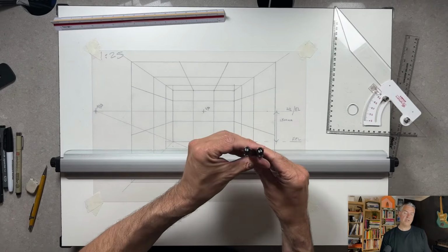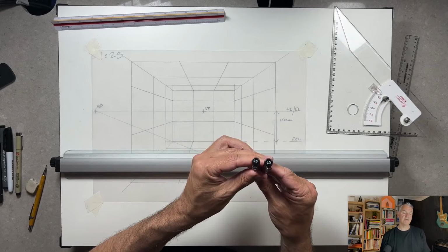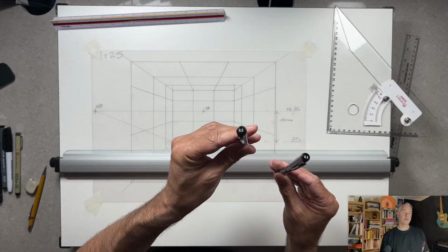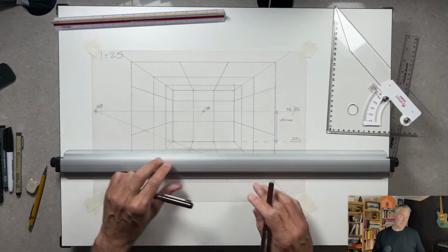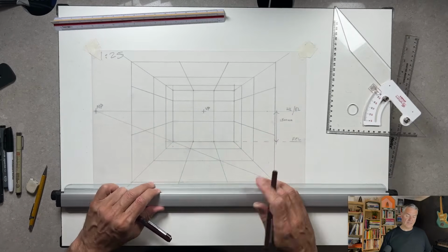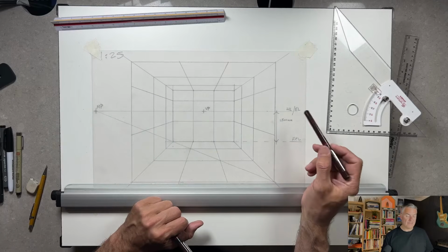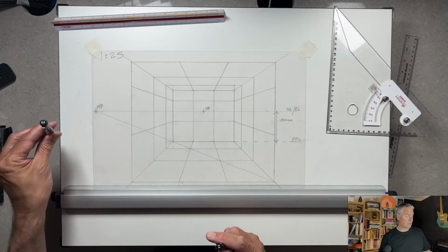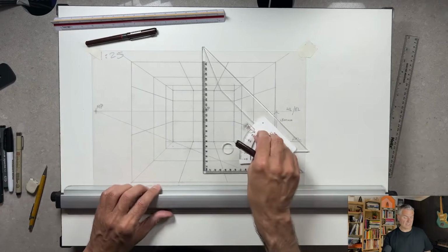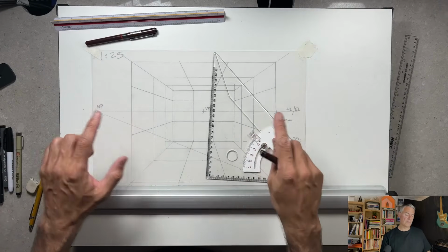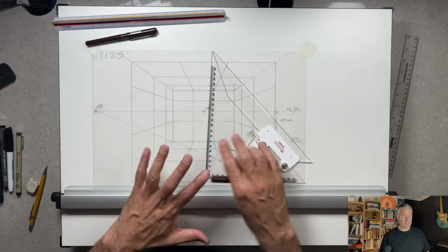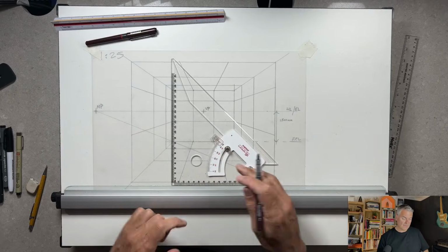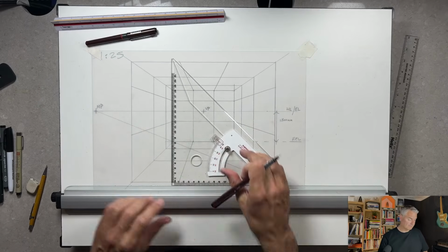So I'm basically going to use two thicknesses of pen here. So a 0.3, which is a little bit thinner than a 0.5. And so I'm going to basically draw the whole thing in a 0.3, and then I'm just going to fatten up some of the outer edges, which you'll see. So everything you'll see being drawn, I'm not going to draw the 0.5 over the 0.3, but I'm just going to draw all the things in 0.3 so you can, and then I'll stop to show you, and then we'll put all the 0.5 in.